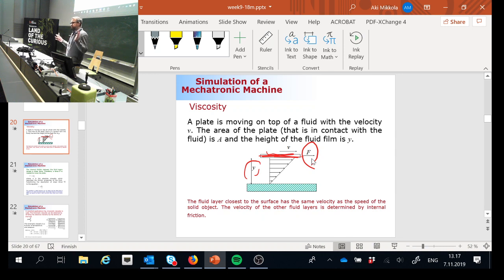The force is imposed on the plate, and because of the force, it reaches a constant velocity, because of the way Newtonian fluids behave. The velocity of the plate will be v here, and Newtonian fluids behave in such a way that the fluid particles close to the plate, right next to the plate here, have roughly the same velocity as the plate itself. Then there's another extreme, the fluid particles that are close to the surface that is standing still.